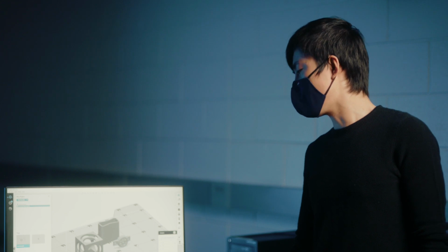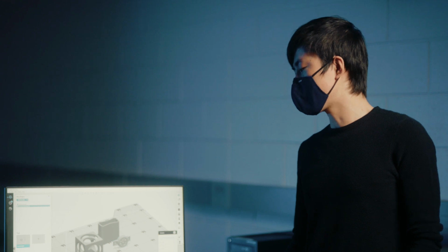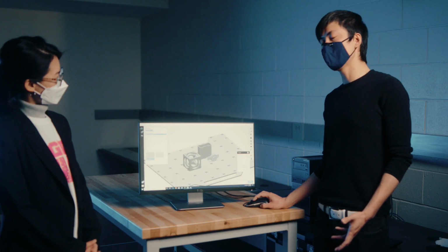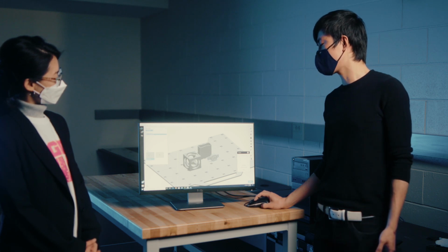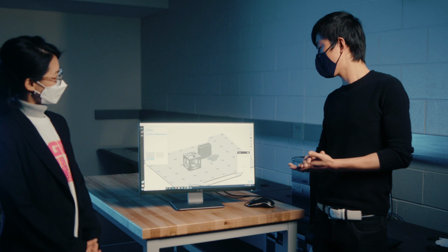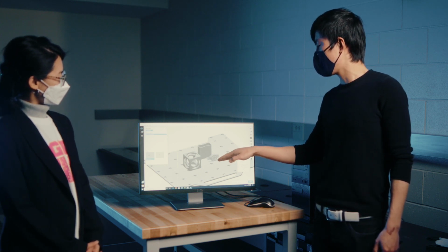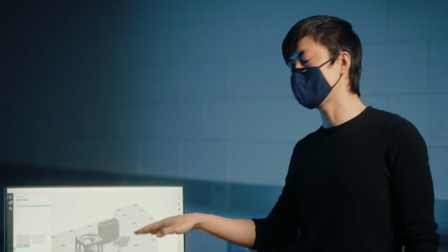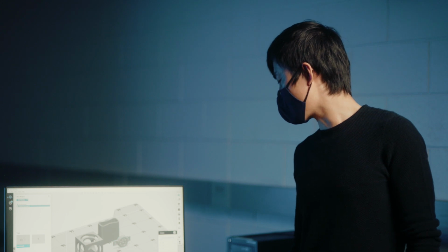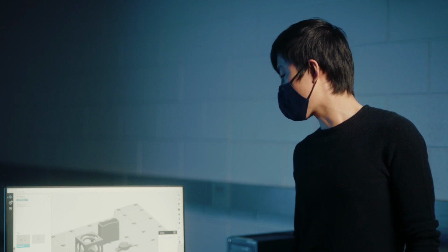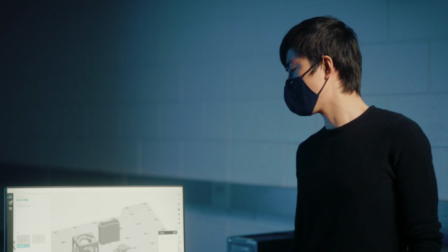If you import your model and it looks like this, it can still be printed, but it won't come out as accurate as you want it to be, because the way the printer works is they print it layer by layer. So you can see the circle profile here. When we finish printing, the surface finish will not be as smooth as you want it to be. To get the best result, we actually want to lay it flat. In this case, it uses less support material and has a good finish.